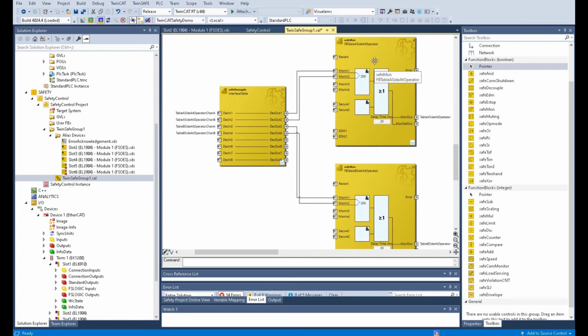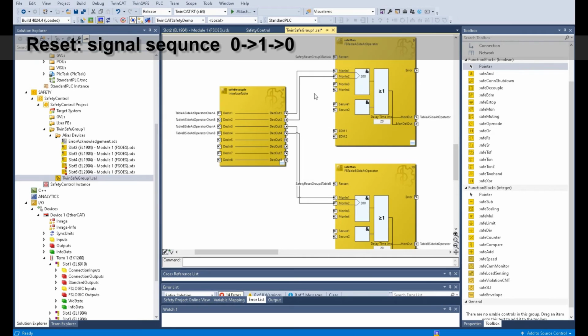For the turntable, this turntable is a little bit special because it will work in every cycle. So that reset cannot be only controlled by the MCP reset button or the palm out button. Basically, it needs to be reset by itself. From the logic view, we can put a very simple logic, for example, channel A and channel B, and after that, put a TON timer, for example, 100 milliseconds, and then put a TP timer to give a pulse, allowing the reset to go from 0 to 1, then back to 0.